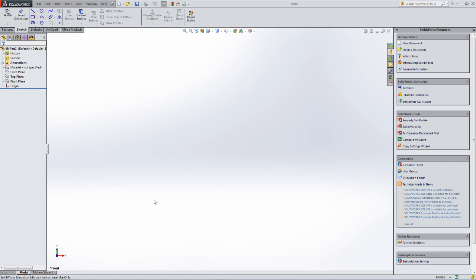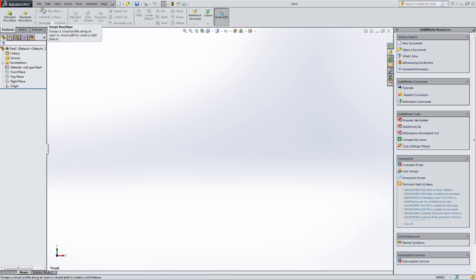To start drawing an aircraft, we need to start by drawing the wing. And the way we'll make the wing is with a function called lofting. Now, a function like that is called a feature. Go up here and we hit the features tab, and you can see there's lofted and extruded things, and we're going to do both of those.